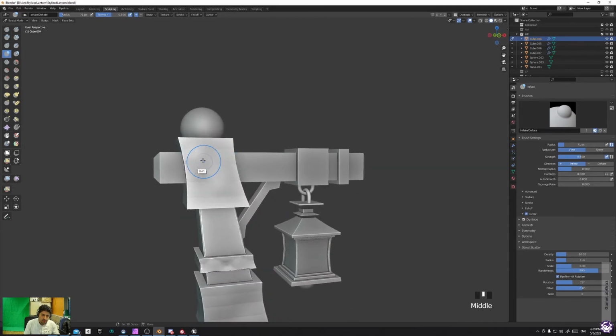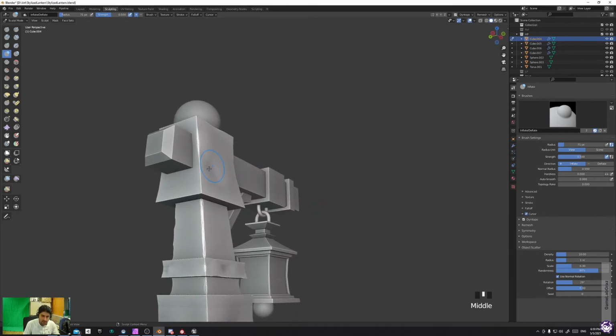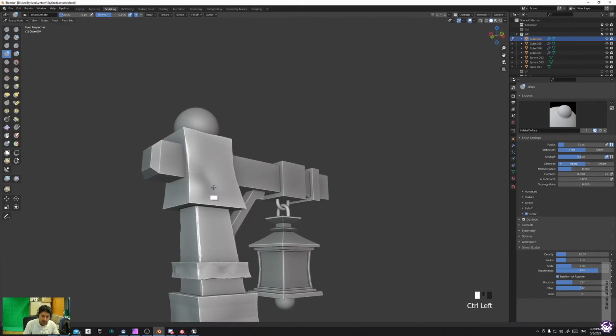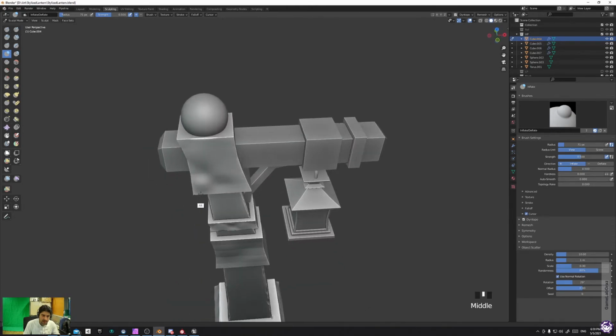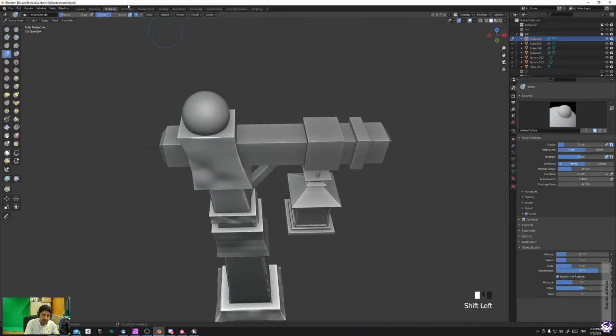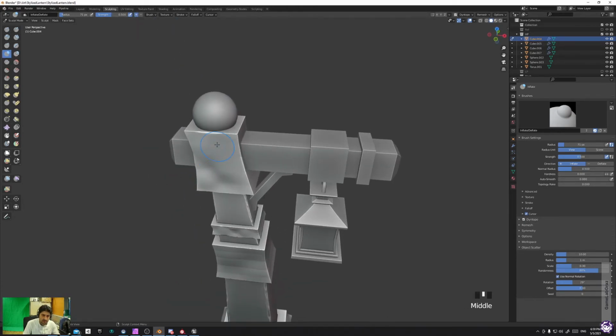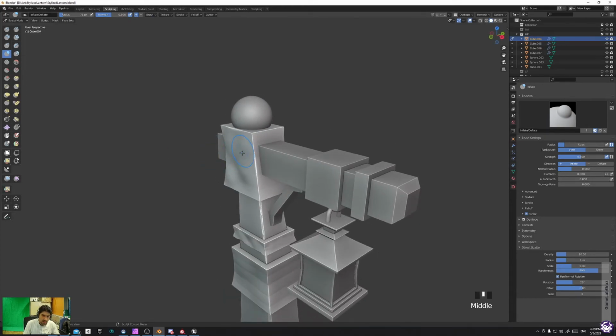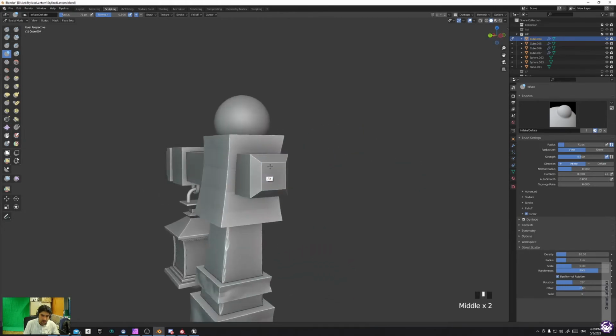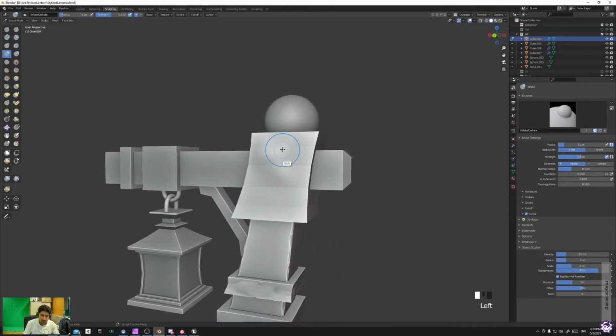In the sculpt mode, by pressing shift, as I told you, you can smooth the parts that you already sculpted, and by pressing Ctrl, you can reverse the workflow that you have. For example, now we are in a positive way, it means everything that I'm drawing is going outward, and when I press Ctrl, everything will go inward. And in this case, you can differentiate.